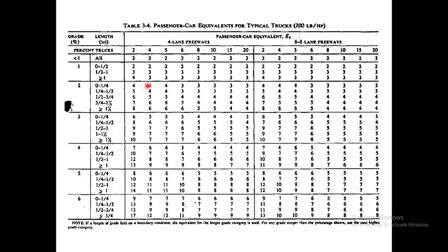Here is the first one. Okay, definitely the number of lanes is important. Again, in most of the tables the number of lanes is important, so always remember the number of lanes. For example, when we say we have a 4-lane freeway, or maybe we mention two lanes for each direction, you have to use the left side. Or when we say 6-lane or 8-lane, you have to use the right side of the table.